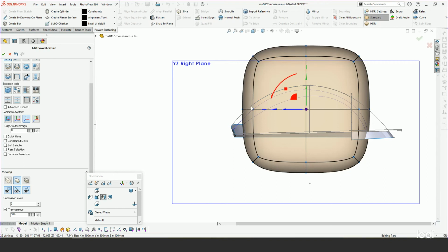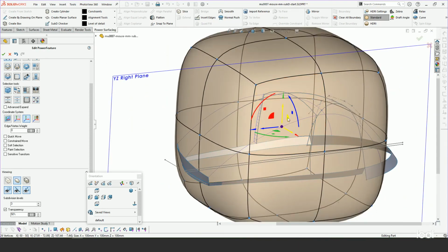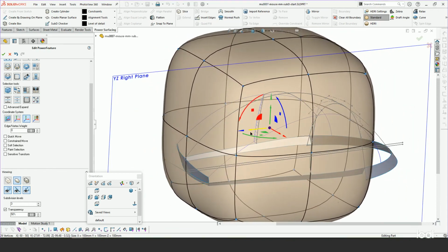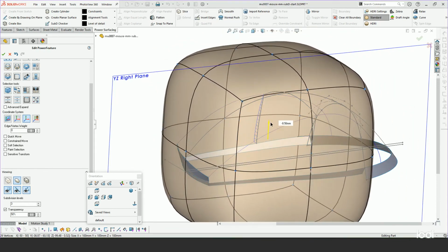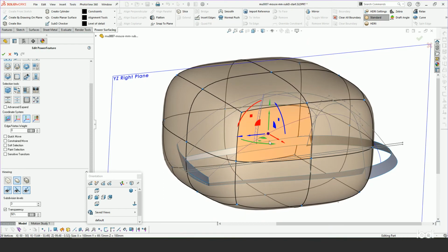So again, as a part of introduction, your work is going to be really focused on the triad. So the triad is much like the SolidWorks triad. There's a bit of difference here. So the inner arrows are translate. So I'm going to translate back and forth with everything selected. I'm going to translate in Y up and down with that one. The arrow right above it is scale. So if you pull on that, you'll scale it in that direction.